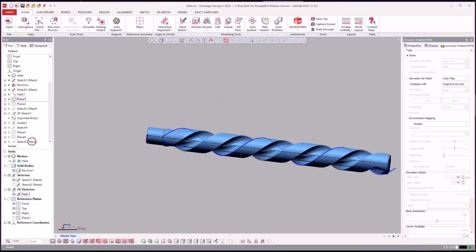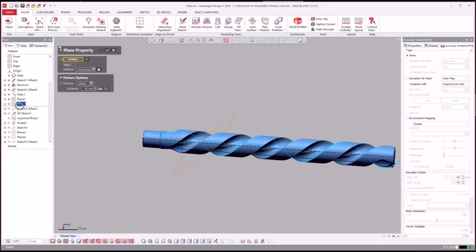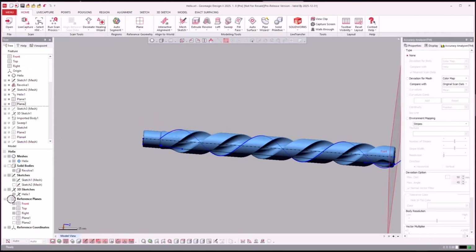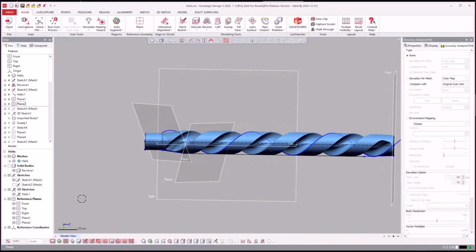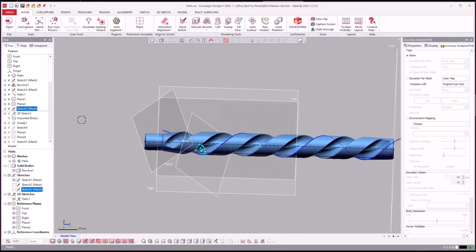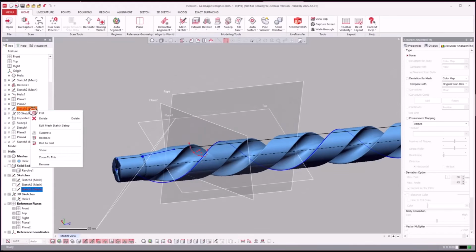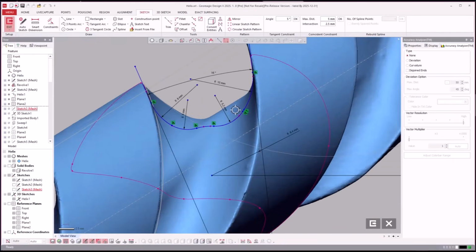So you see they created that plane, and then they created another one here. End division, it looks like they created it. Let's just double check it. End division edge offset. So they created both of those. Just turn our planes on. Right there. All right, so now we'll jump forward. And we use that second plane, created a sketch normal to right here.